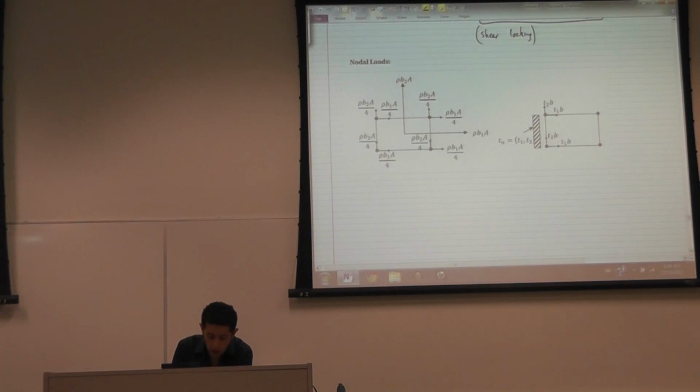If I have a body force pulling the elements, I would like to distribute that body force into forces on the nodes. The force vectors on the nodes will be equal to the matrix N transpose multiplied by rho B, integrated over the volume, where B is a vector made out of B1 and B2.